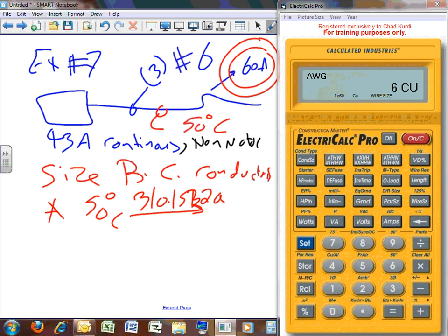B2A. And the insulation is THHN, because I chose THHN, the most typical insulation you're going to encounter. Okay, so can you guys find me the derating factor based on 50 degrees, based on this table 310.15 B2A? That will give you 90, by the way, that will give you 90 degrees, right? Everybody knows the reason why I gave you that, because this means 90 degrees Celsius. So what's the derating factor for 90 degrees Celsius?